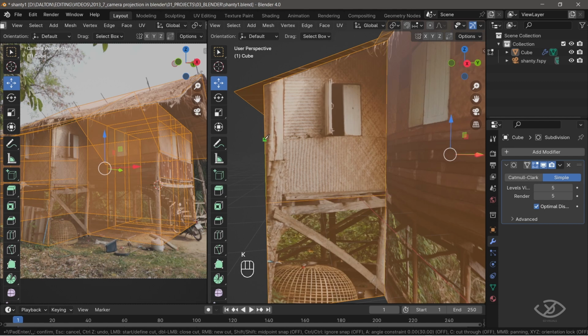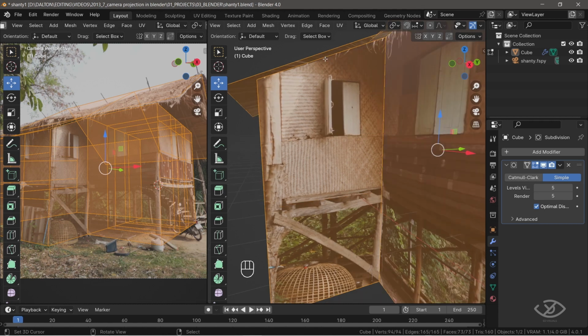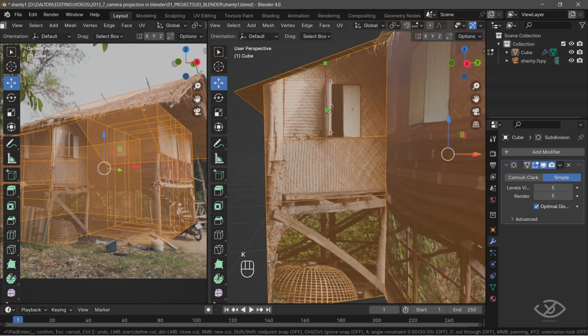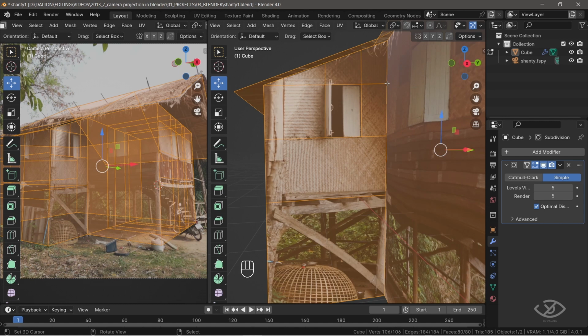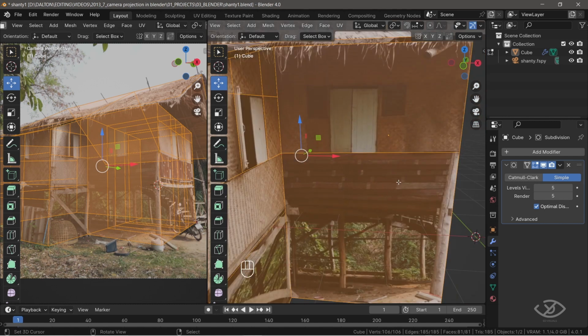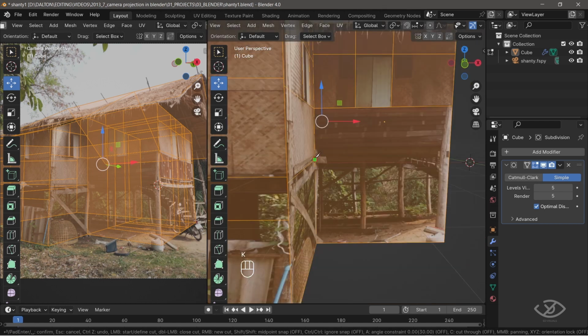Simply press K and drag it to the areas where you want to add some edge loops. If you encounter a knife tool issue like the line disappearing when making 2 points, you simply press C on the keyboard to constrain direction. You can also adjust the individual edge loops to properly align the edges. This process can take some time, so be patient, because the more time we spend adding loop cuts, the better quality because we can add more details to the object we're working on.